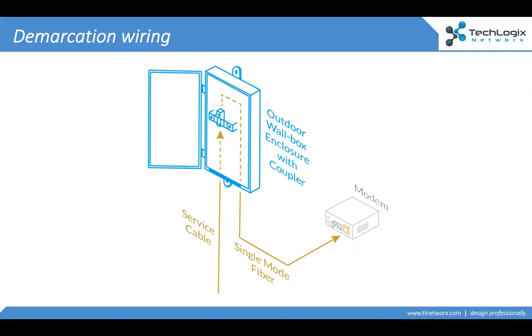Here's the thing. You've got to make sure you're pulling the right type of fiber. And this is a problem that we see in a lot of installations. People think that fiber is fiber, glass is glass. That's not the case. Remember, single mode versus multi-mode. There's a reason we talk through this. Single mode fiber, that's your long distance cable. That's your small core size. And you have to pull the right type of fiber if you're connecting to the service feed, the telecom, the ISP, call it what you will, but the cable that comes into the property is going to be single mode fiber. And if you're pulling fiber to the box to meet it, to couple it, to splice into it, it's got to be single mode fiber. Any cable before the modem has to be single mode fiber. Pull single mode, you're in good shape. Now, once you get past the modem, you do whatever you want. It can be single mode, it can be multi-mode, it can be twisted pair, okay? You have options. But if it's before the modem, it's got to be single mode fiber.